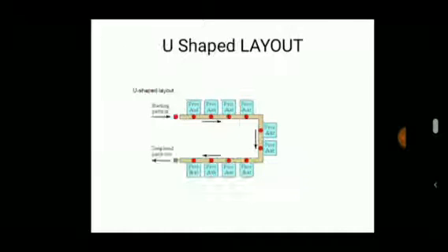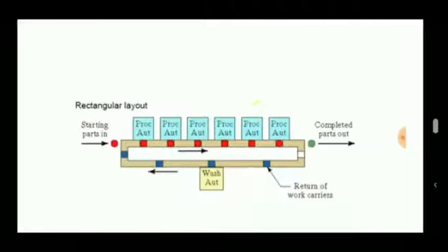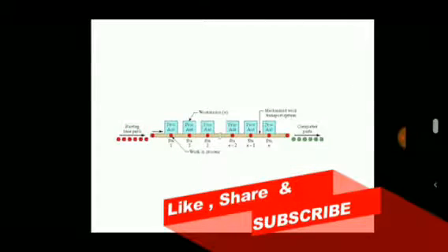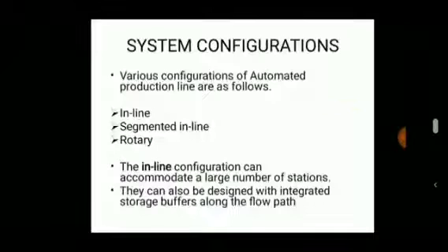We can see this in this diagram. These include palletized stations and palletized workpieces. The workpieces are held in the pallets. The pallets are moved around and then washed, and finally they come back to the beginning stage. This is an example of palletized fixtures.